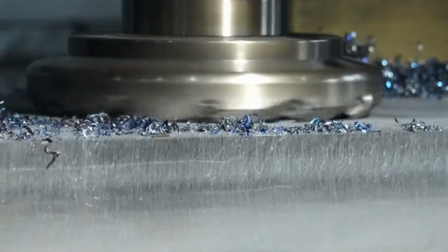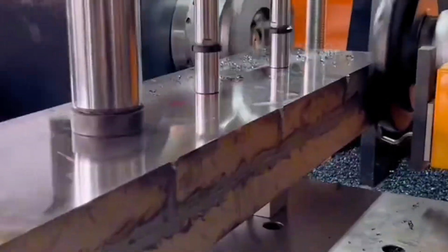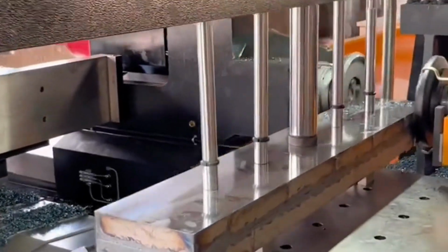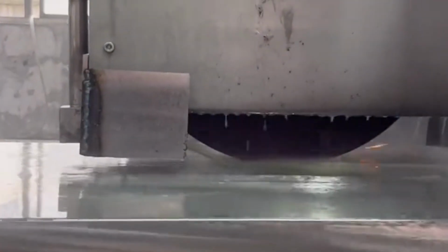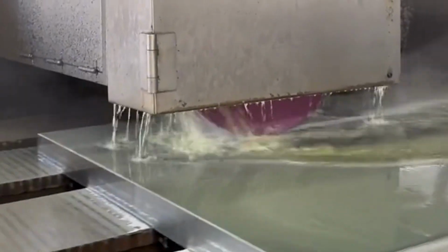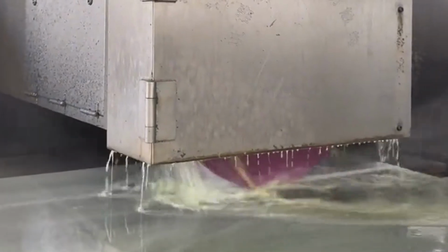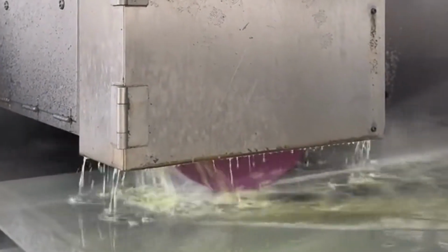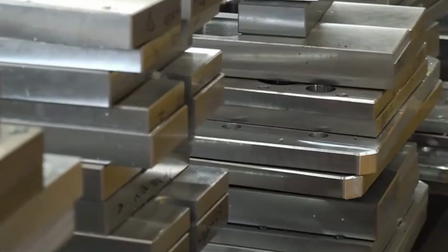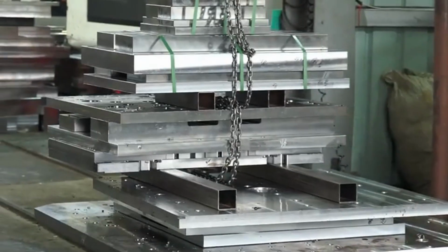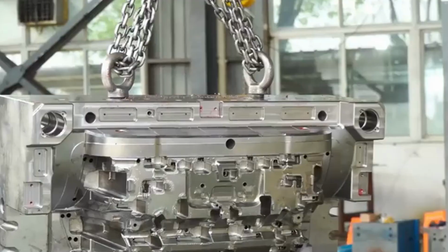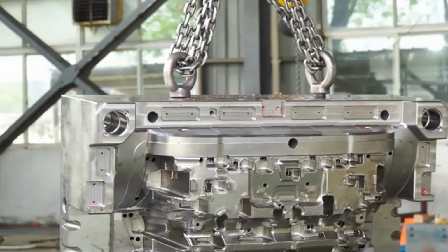For some high-precision transparent product molds, you may also choose S136 steel, a corrosion-resistant mirror plastic mold steel. This steel has better corrosion resistance and polishing performance, and can effectively prevent surface defects such as rust spots, so as to ensure the appearance quality of transparent products.